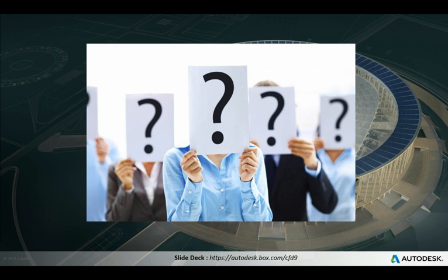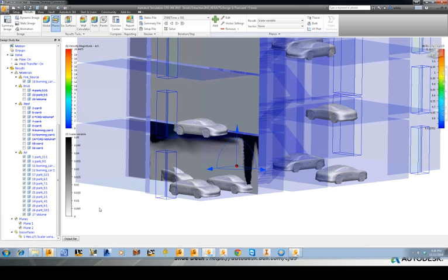I guess what's worth mentioning is where it wouldn't work is if we were modeling radiation, we couldn't have more than one slip symmetry, right? Right, for the most part, as long as it's periodic around that slip symmetry, because what we do in the background when you set up a true radiation model is that it rebuilds that mesh to develop a full model to calculate all the view factors. So if it can't accurately replicate that on either side of the slip symmetry, then that will fail.